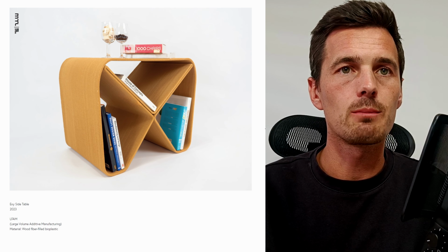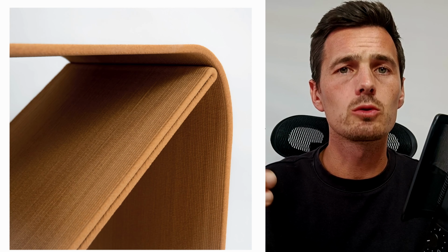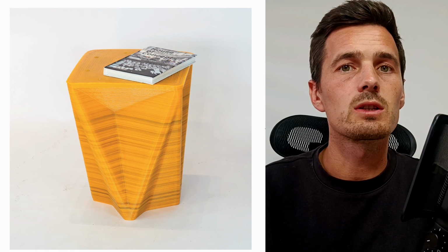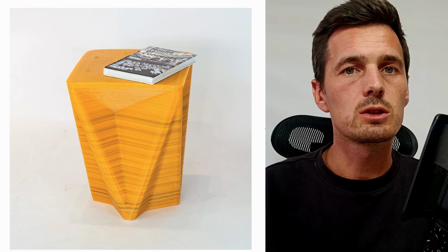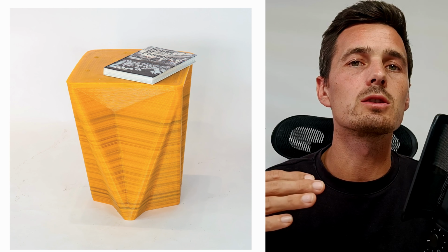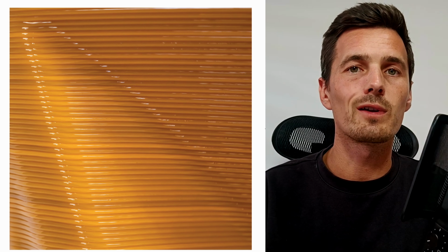This is another example of a bioplastic filled with wood fibers. So it has more of a wood kind of texture. Also the smell, if you print it, is more like wood. And this one is made of PET, the material that's used to produce water bottles. It has a more shiny look. It does tend to get more brittle. So if you use something that needs to hold more strength, for example a chair that you want to sit on, be aware that over time it can get too brittle and it can break.